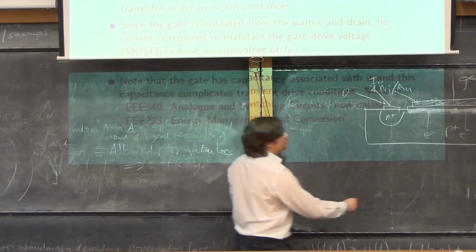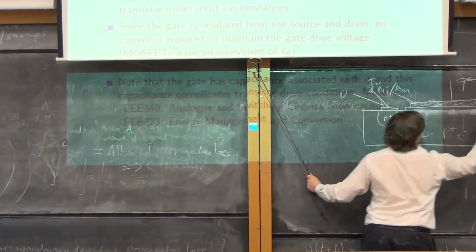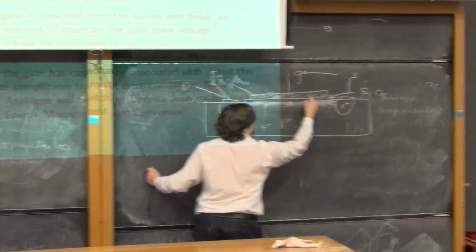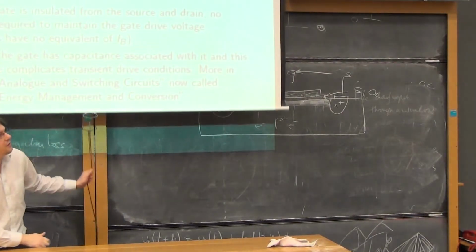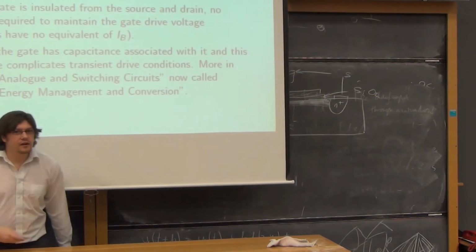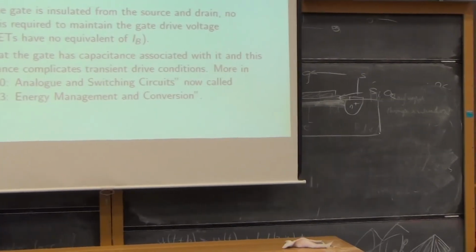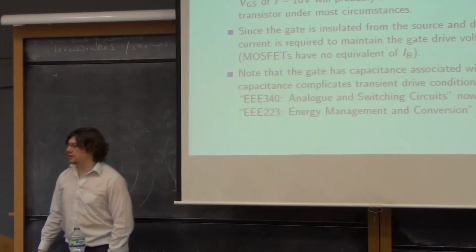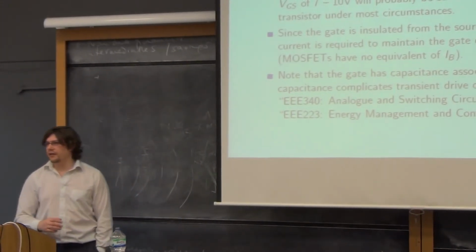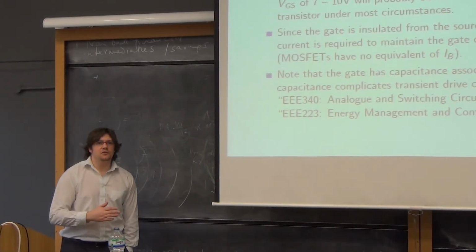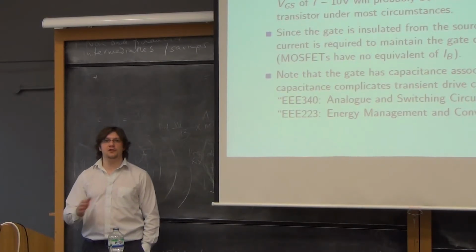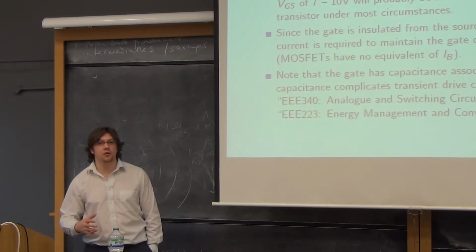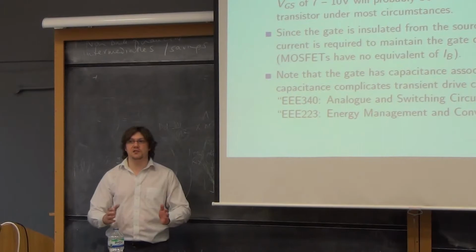If you want to put a voltage between there and there, you have to put enough charge on that gate to charge up that capacitance. That's how the gate capacitance comes into being. In later modules, you'll worry about how long it takes to charge up that gate capacitance, because when you're charging it up, you'll turn the device on, and that process takes some time.